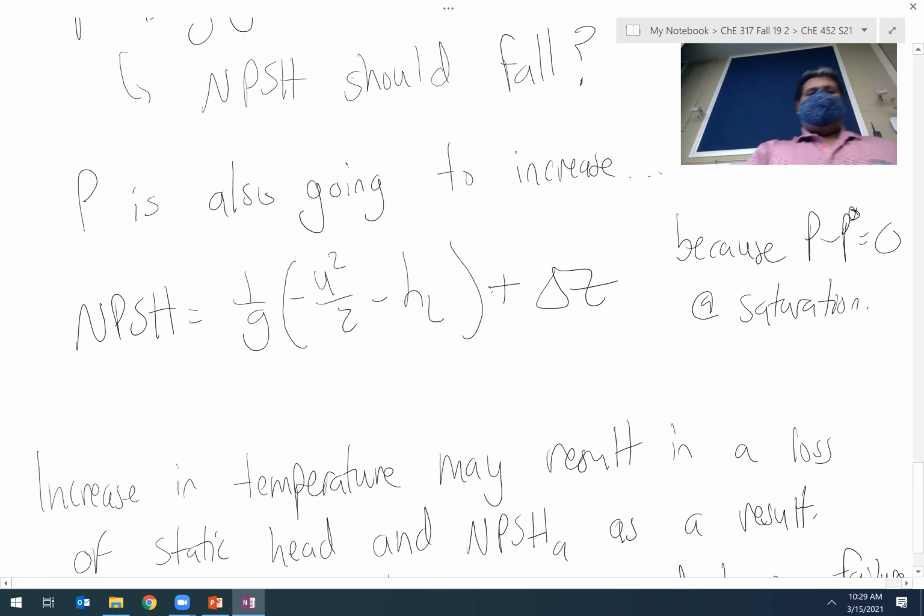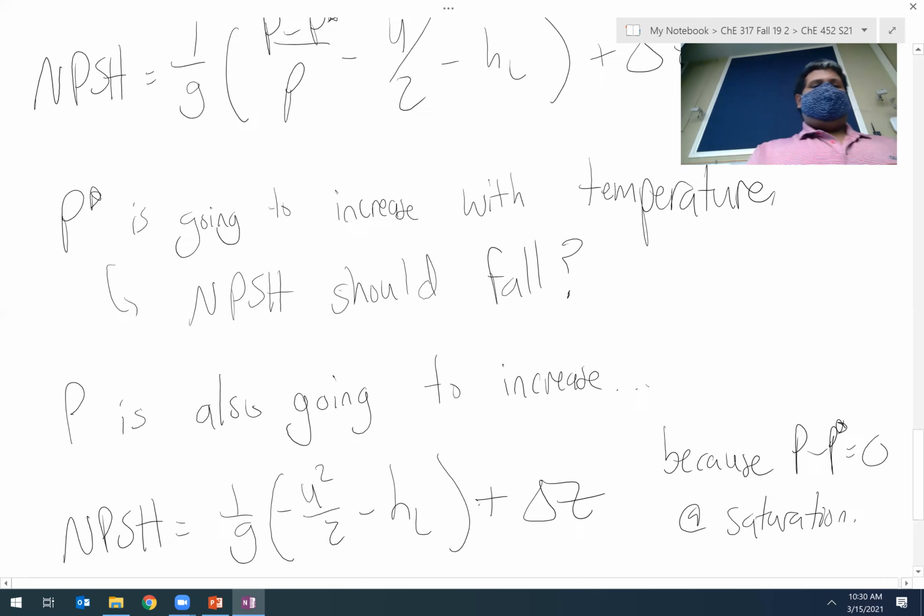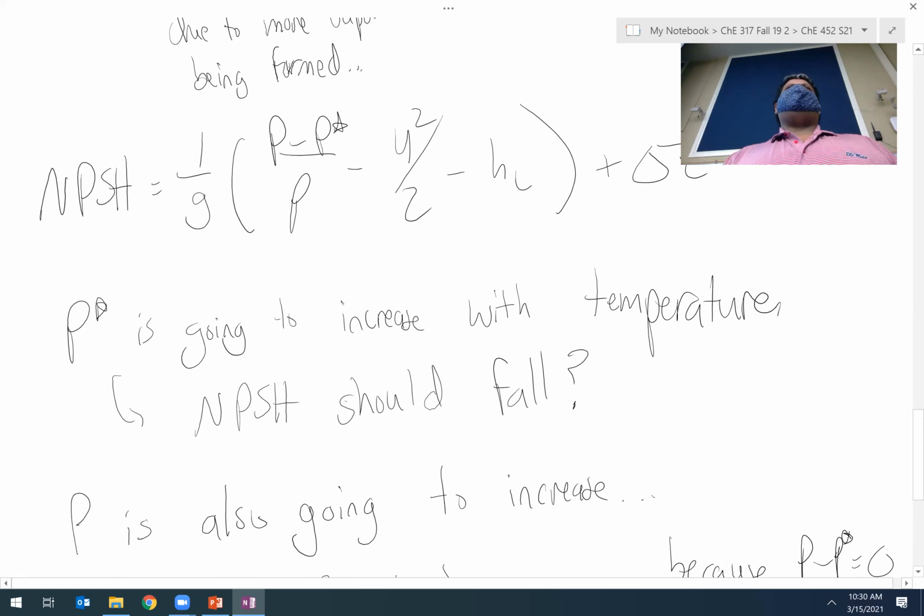And so the purpose of this problem in the exercise is that a lot of times looking at our key expressions can give us clues about what would and would not cause issues we see in a process. In this problem, the kind of easy answer is to say, well, the temperature rose, which means there's more vapor. We're closer to the vapor, boiling point. I expect the vapor pressure to go up, which is going to cause cavitation. So, bad system.